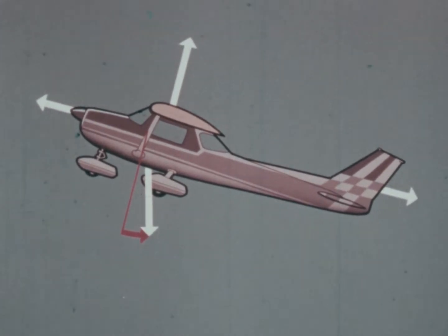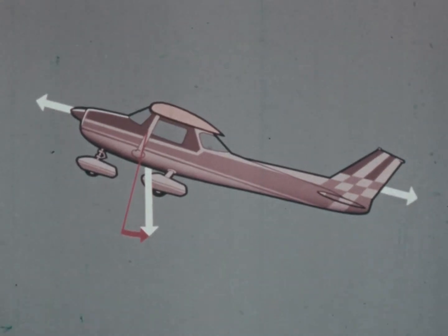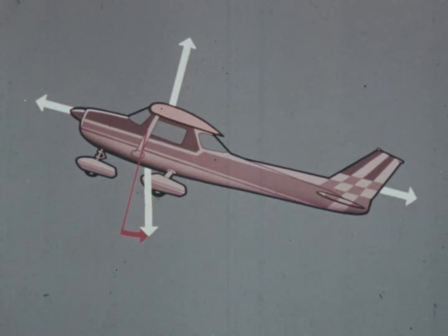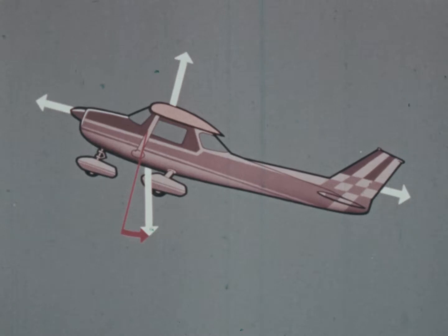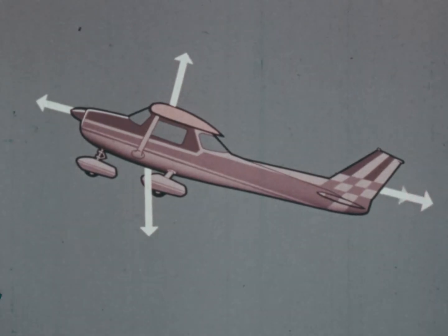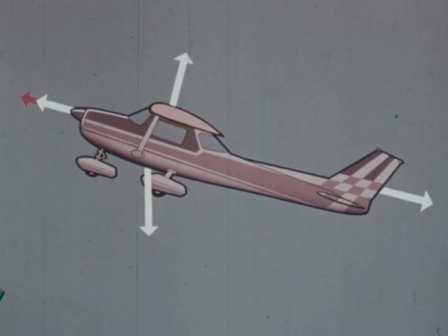This directional effect of the weight on drag slows the airplane down in the climb, so that both lift and aerodynamic drag are reduced. But if we add the drag effect of weight to the remaining aerodynamic drag, the total drag becomes greater than in level flight. To keep the forces in balance, thrust must be increased to balance the new force of drag plus its component of weight.